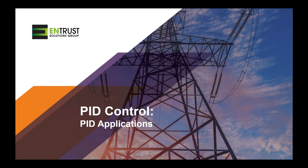And one of the questions that was asked is, do you like to do this online or offline? And I think that kind of depends. Recently, we had a situation where we were implementing a new PID controller, and we were able to simulate some upsets prior to putting the system in service, and that can help you get a baseline. And the more complex the system is, the more you're going to have to do tuning online, just because it's hard to simulate all the possible scenarios.